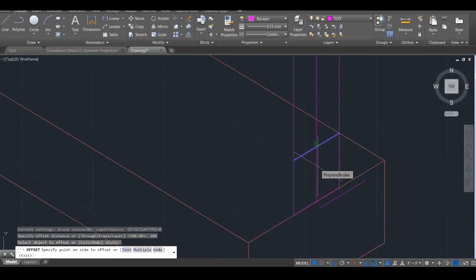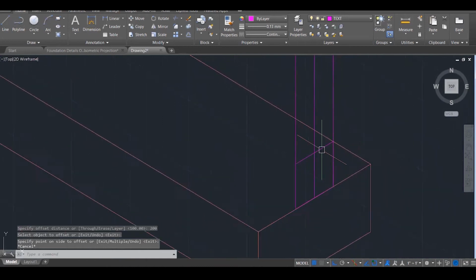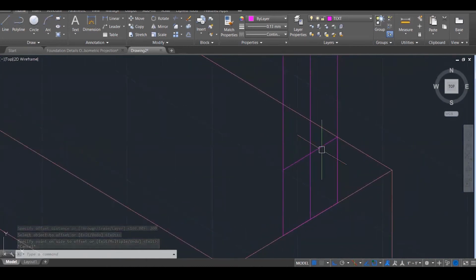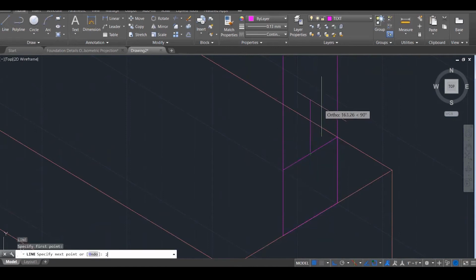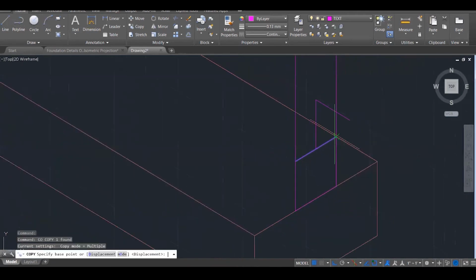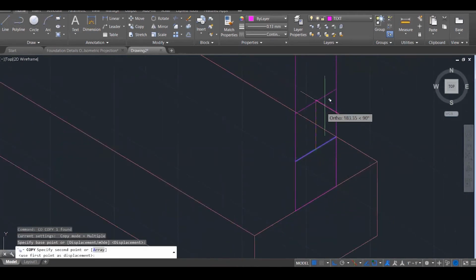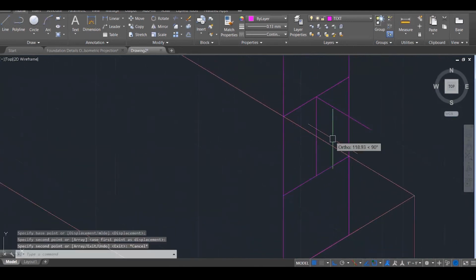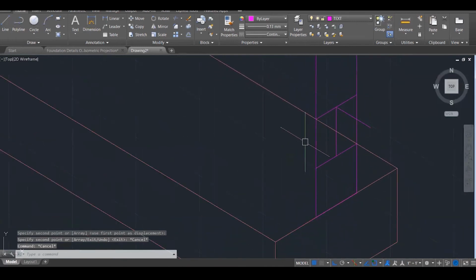I would not advise you guys using the offset tool here when you're trying to insert distances. No, I wouldn't advise that. I would advise you guys to actually go around and draw a line like this and go up 200 because that's the distance I want, and know where your 200 indicator is. So you could do something like this, and then you can copy that in place there, like 200. It's probably the best bet. Can't go around doing something like that.